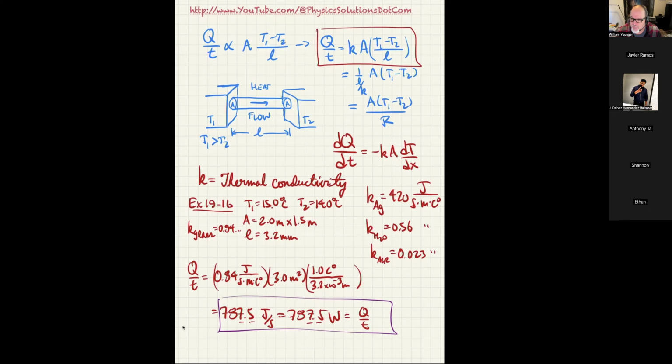But that's because we found experimentally that on low wind days, there's generally a little cushion of air just outside of the window that stays there, usually at some temperature between the air temperature and the indoor temperature. Then there's another wafer of air on the inside of the window that's closer to the temperature of the window and what's outside than inside the house. So that little wafer of air on each side provides a modicum of insulation to make the windows a little less awful.